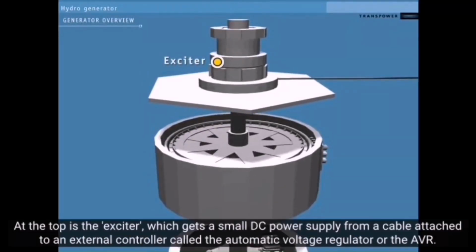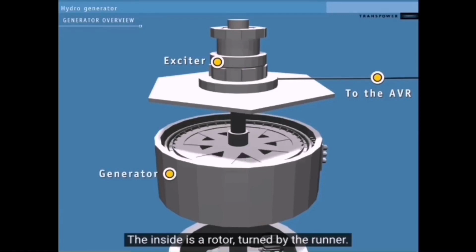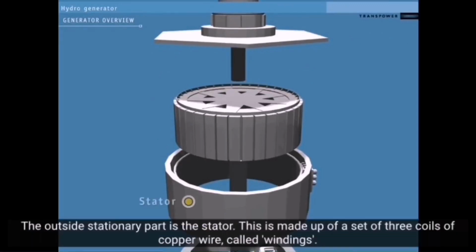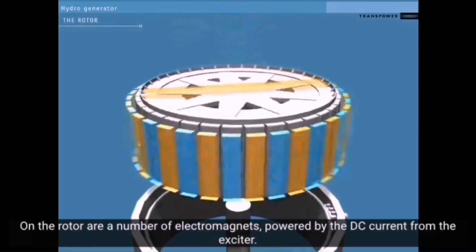As you can see, this is the part of the generator. From the top is the exciter, which gets a small DC power supply from a cable to the automated voltage regulator. Below the exciter is the generator. Inside the generator, there is a rotor that is turned by the runner. And the outside part is called the stator, which is made up of a set of three coils of copper called windings.